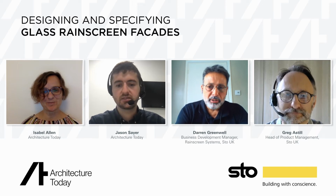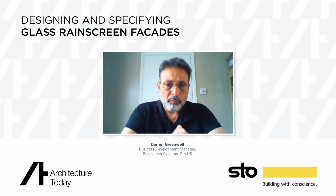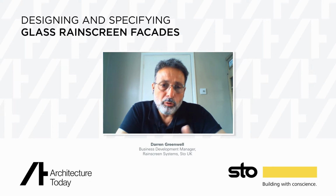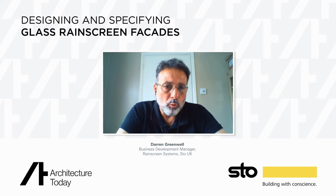Yeah, absolutely. System build-up, as a Rainscreen system or an insulated Rainscreen system, the primary element is the insulation. Everything else is sort of icing on the cake and subconstruction. So it's achieving whichever U value target you're looking to achieve. Let us know what thermal targets you have, and let us know what the actual structural wall build-up is.